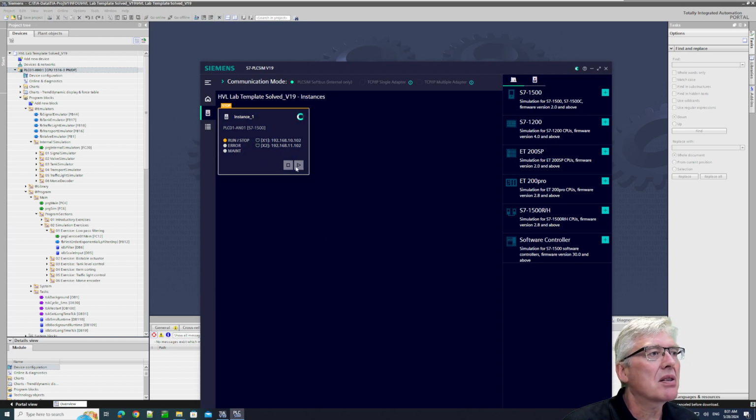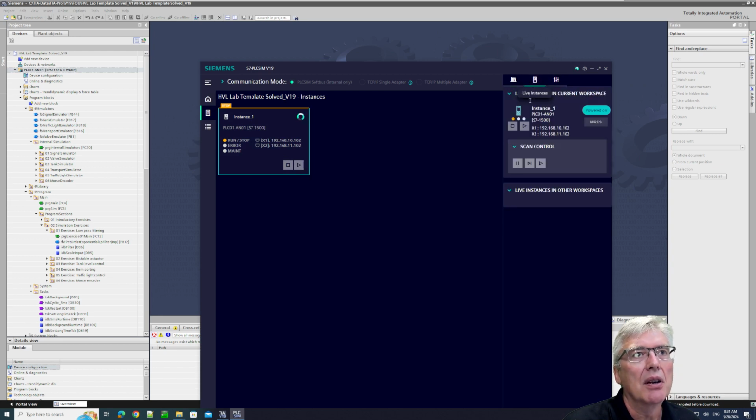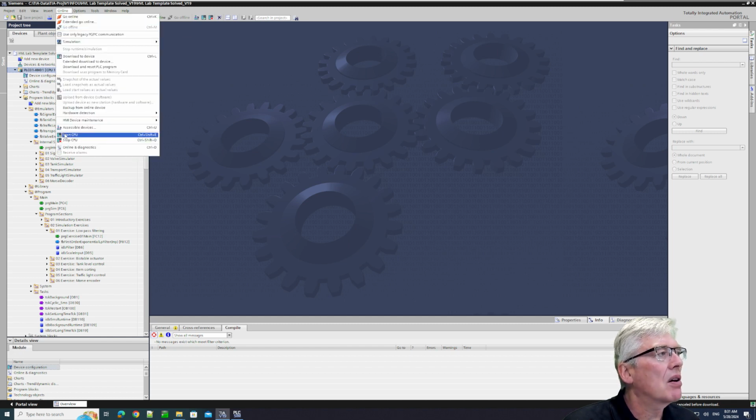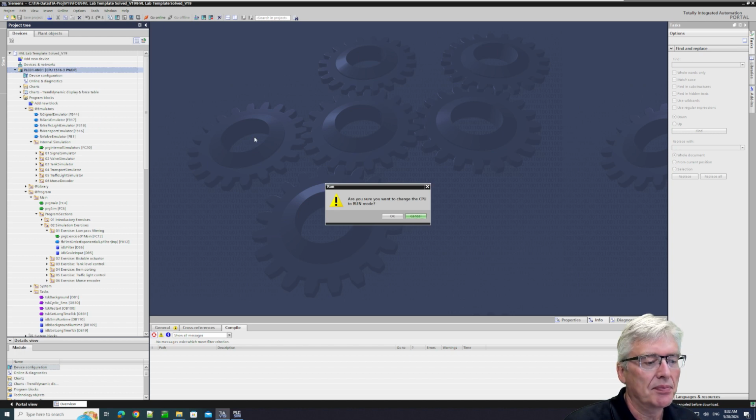And okay, it's not running. These are grayed out, so I can't select those. It's powered on. Yes. Can I select run here? No. This yellow light is the same orange LED you have on the front of your CPU, but I can't select run. But it seems to be under power. So let's see over here, I say online, start CPU. Here is an option. Yes, that's why I asked for it.